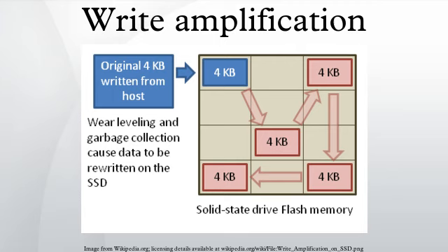If the user or operating system erases a file, the file will typically be marked for deletion, but the actual contents on the disk are never actually erased. Because of this, the SSD does not know the LBAs that the file previously occupied can be erased, so the SSD will keep garbage collecting them.